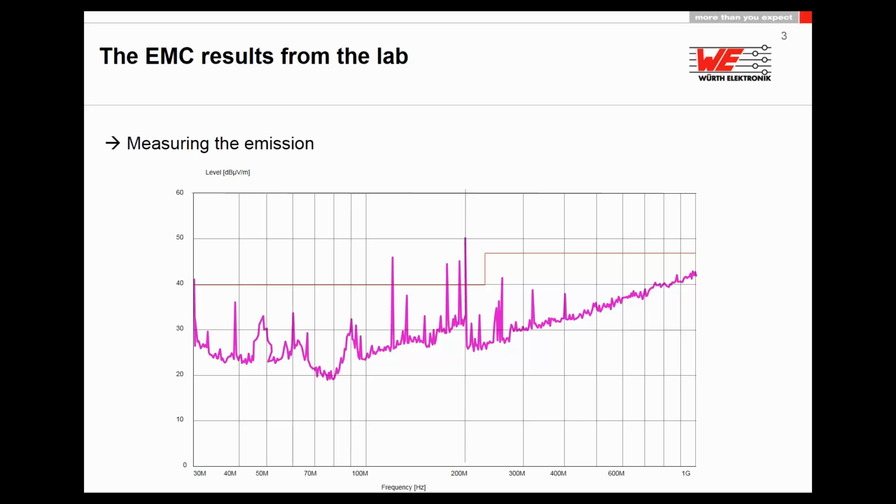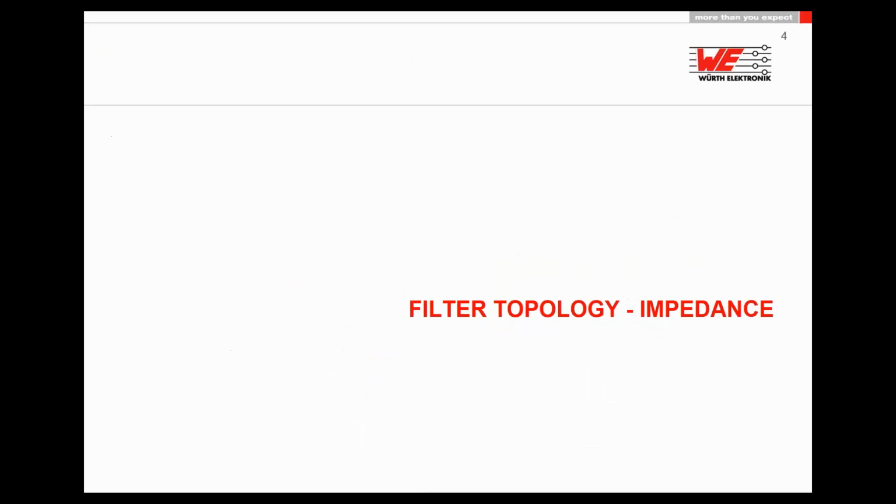First of all, try to check what is the maximum peak in your scan. When you see this maximum peak is roughly around 200 megahertz and you have a peak which is almost 20-21 dB, always try to filter this frequency. When you filter this frequency, there are also side effects from this filter, because you will not have a filter which is cutting exactly only 200 megahertz, it will also filter some additional harmonics. But this is a long way to that.